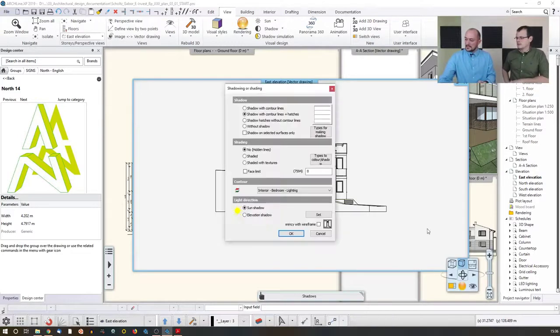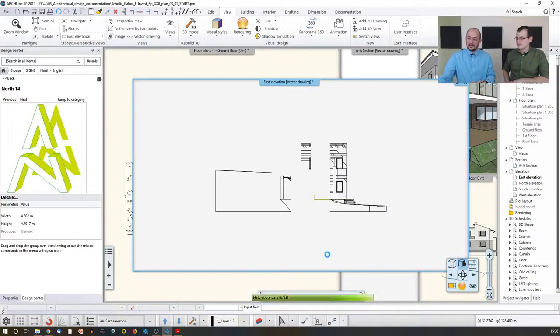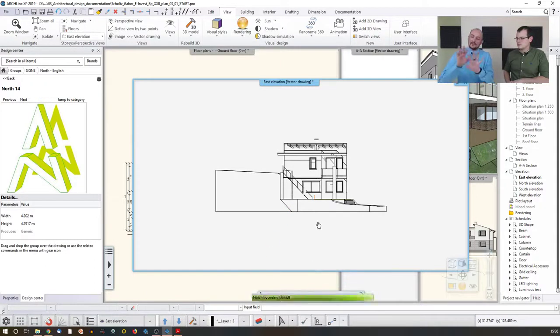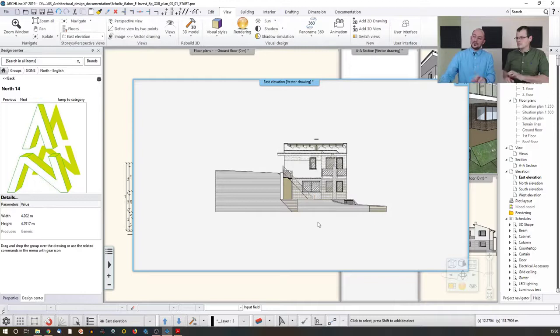Then let me just quickly set the same settings up here. Okay, there's shaded and elevation and shadow contours and so on. So the software creates that, and then I go back to the selection. I will select the whole drawing, make a copy of it. Sometimes it takes longer because now the software is calculating all the shadow contours.